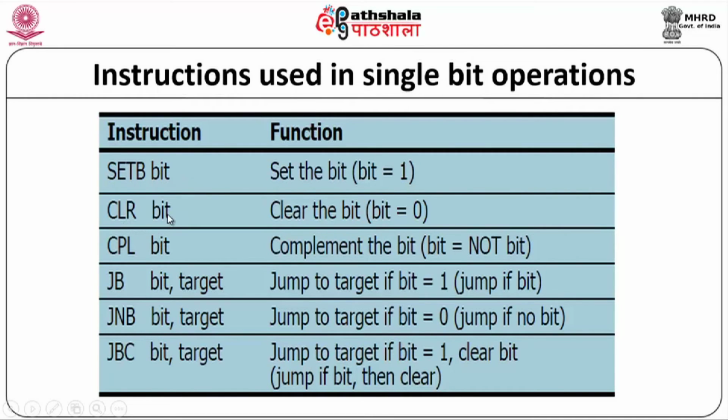To clear a bit, if I give CLR P1.0, then the P1.0 pin is equal to 0. So clear, or reset, is done through this CLR opcode. CPL is nothing but complement.